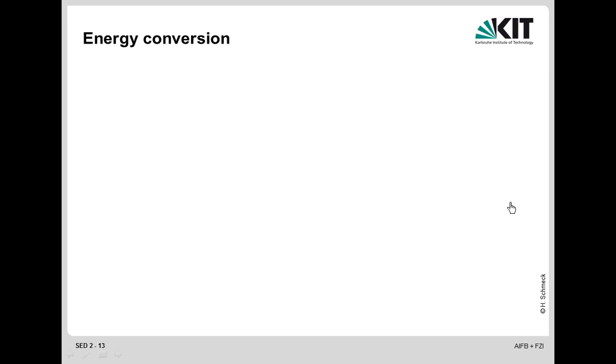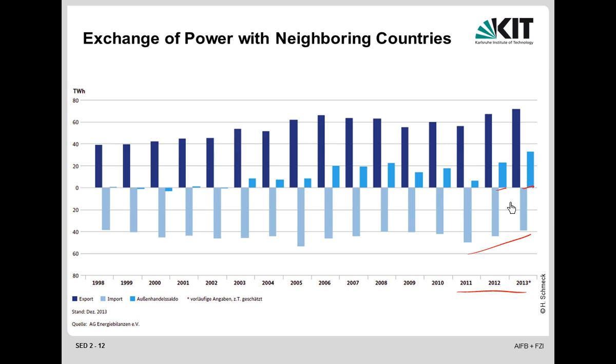Like on last Sunday, 86% of the electrical power consumption was covered by renewables, by photovoltaic and wind. It means only 14% by the conventional power plants, which have to run through. And so the prices on the intraday market went down to minus €100 per megawatt hour. So that means that you were paid significantly for consuming power, because there was such a surplus that we had to get rid of it.